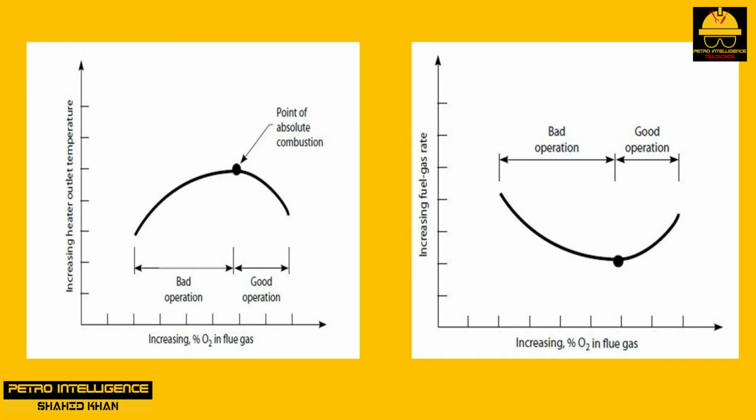Also, while continuing to fall below the point of absolute combustion, we accelerate the production of atmospheric pollutants such as aldehydes, ketones, light alcohols, carbon monoxide, and other products of the partial combustion of light hydrocarbons in the stack gases.